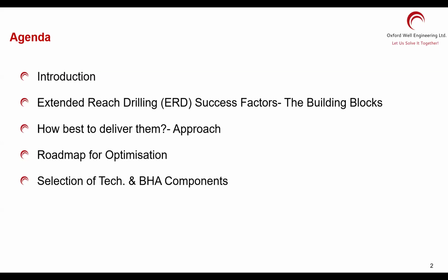Because in normal drilling, you may not be worried about downhole weight on bit. You may not be too worried about downhole torque measured by sensors. But here in ERD, it's gold. This is what you need. Why? Because you have an eye in the borehole. That way, you are seeing the problem that the BHA is negotiating.